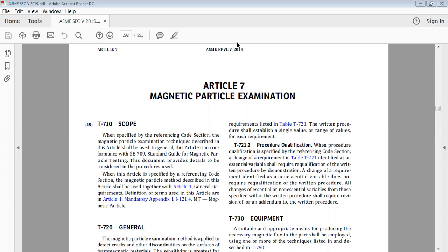How do we do this? We take a 100 ml bath sample in a centrifuge tube from the main bath and wait for 30 minutes. After 30 minutes, the iron particles settle at the bottom of the centrifuge tube, and there is a marking. We read that, just 0.1, 0.2, 0.3. In this way we measure the settling test, meaning concentration.